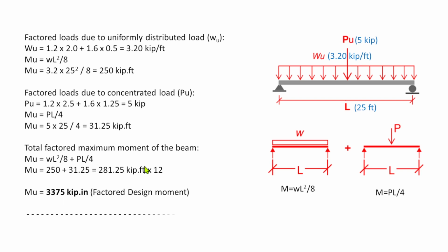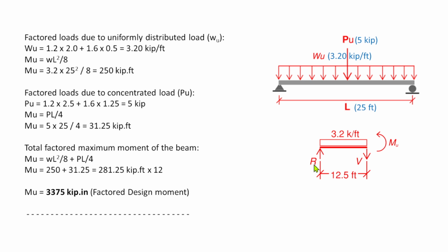kPa. By the way guys, if you forgot all these formulas, there is another way of calculating this moment. If you notice, our beam is symmetrical and the loading is symmetrical, so what you're going to do is just sum up all the loadings, then divide by 2, and you will get the reaction at the support. You don't need to draw the moment diagram or do the summation of moments, because it's very lengthy. That is only if the loadings are symmetrical, similar to what we have.